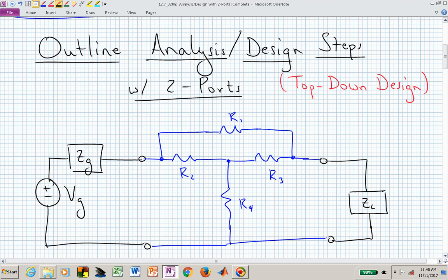Let's assume that we now have this interconnected circuit, and if you were simply analyzing this, you could do a mesh here, a mesh here, and a mesh here, and so you have now three mesh equations, but they're kind of coupled and interconnected. And when you finally find what this current is over here in this lower right hand side, it may be not that intuitive how to select R sub 2 or R sub 1 in order to make that current or the power at the load what you want it to be. Or you could maybe perform some nodal analysis.